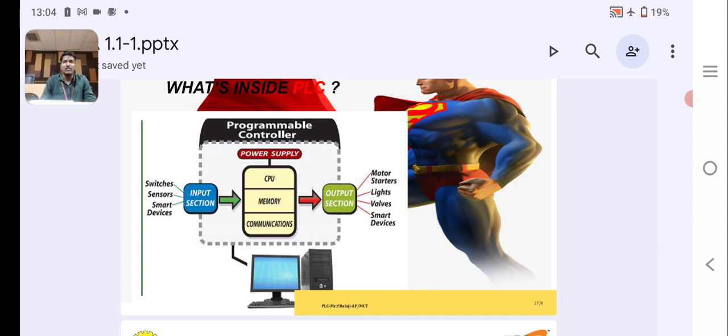Before seeing the scanning process, we can look at some internal architecture of PLCs. It consists of the CPU, microprocessor, memory, and input output circuit, and it also has a clock frequency, typically 1 to 8 megahertz. The frequency determines the operating speed. The clock provides timing and synchronization for all elements of the system. The interface within the PLC is carried out by means of digital signals.